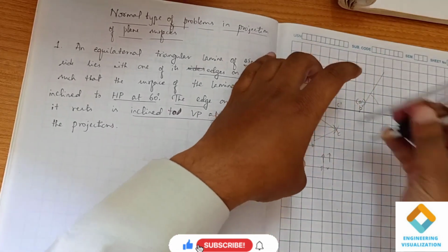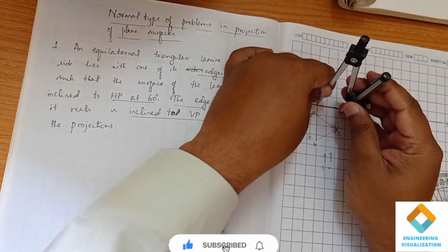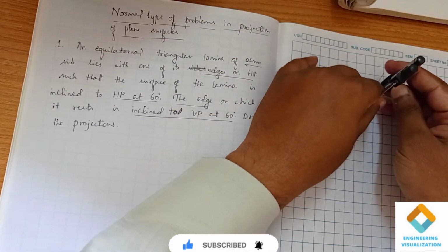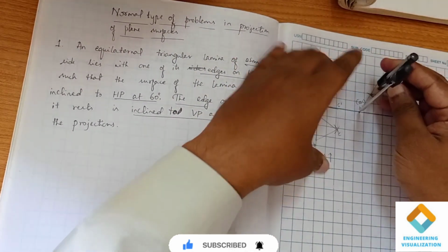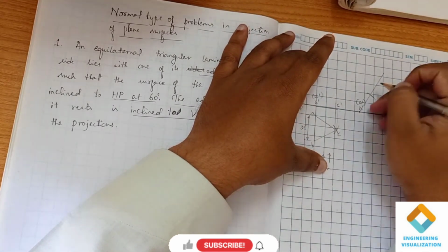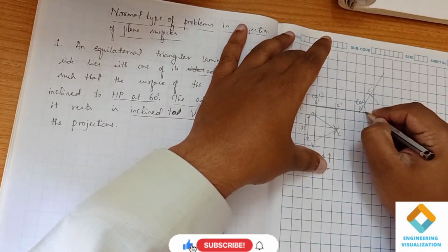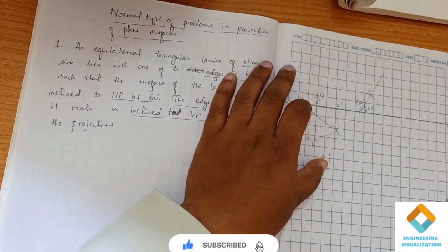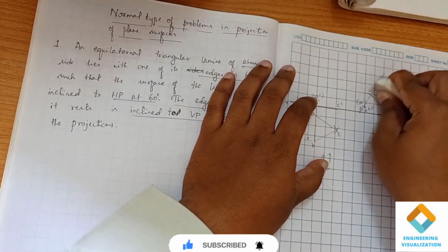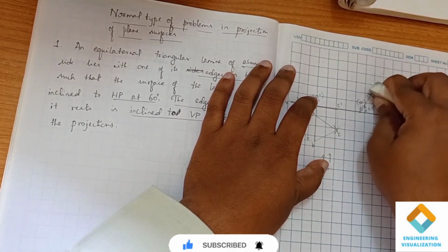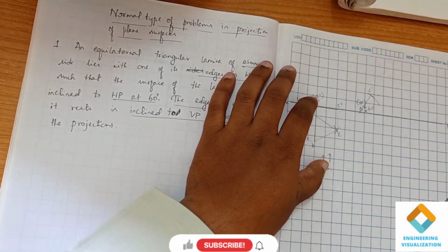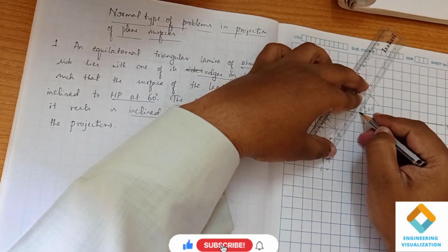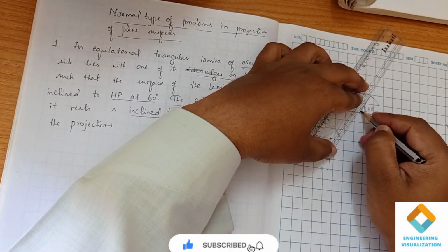Now again I will measure this length, B dash C dash, and extend this arc. The angle we got here is 60 degrees. After getting this length we will rub it, so this is the actual length we require here, till here. I am going to darken this length. This is the length we actually require.